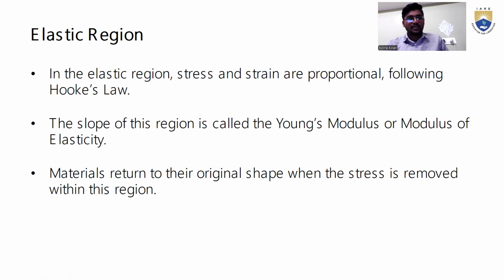Here we see the elastic region. In the elastic region, stress and strain are proportional, following Hooke's law. Hooke's law is nothing but stress is directly proportional to strain. We call it Hooke's law, and also Hooke's law is valid only within the elastic limit.